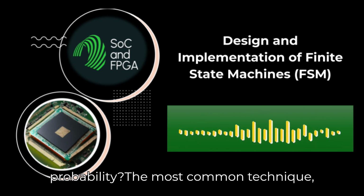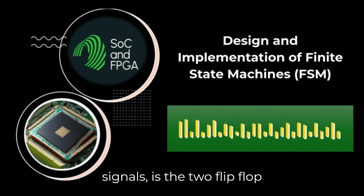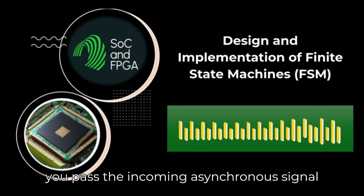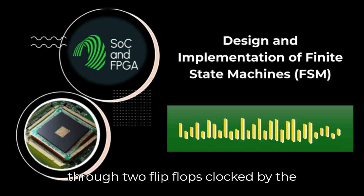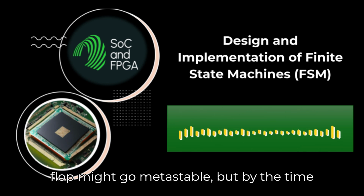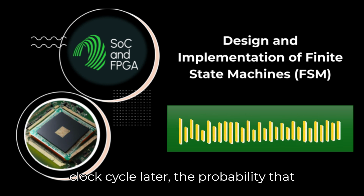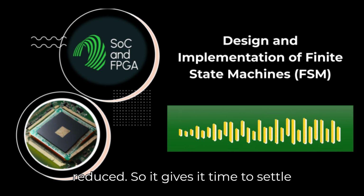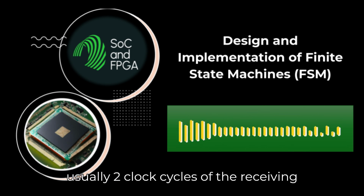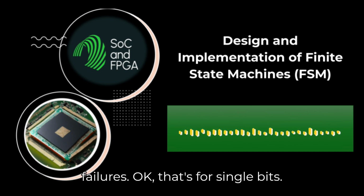The most common technique, almost the default for single-bit control signals, is the 2 flip-flop synchronizer, often called a 2FF synchronizer. 2 flip-flops in a row. Yes, you pass the incoming asynchronous signal through 2 flip-flops clocked by the receiving domain's clock. The first flip-flop might go metastable, but by the time the signal reaches the second flip-flop 1 clock cycle later, the probability that it's still metastable is drastically reduced. So it gives it time to settle down. Essentially, yes. It adds latency, usually 2 clock cycles of the receiving clock, but it significantly increases the MTBF against metastability-induced failures.